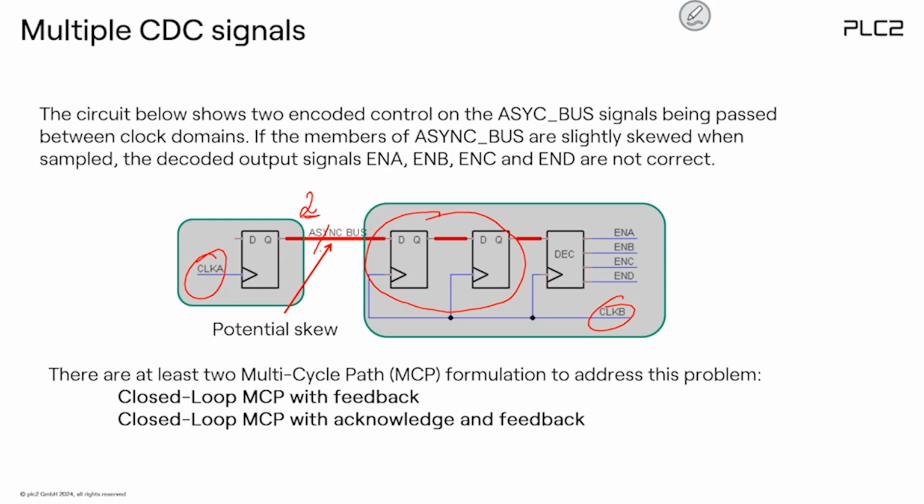And I ran Vivado on this. I never checked this with the latest version, maybe now it works. But in the prior version, Vivado said it's okay, because Vivado did not understand this is a multi-bit signal. So be careful: whenever you have a multi-bit signal here, you will not see this. That's what I did, just for the simulation.